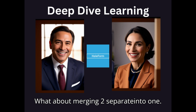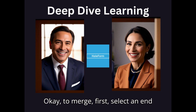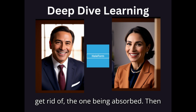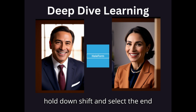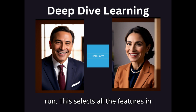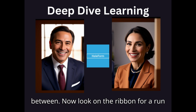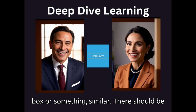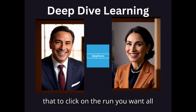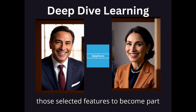What about merging two separate runs into one? Okay, to merge. First, select an end feature of the run you want to basically get rid of, the one being absorbed. Then hold down Shift and select the end feature at the other end of that same run. This selects all the features in between. Now look on the ribbon for a run box or something similar. There should be an option like Select Graphically. Use that to click on the run you want all those selected features to become part of.